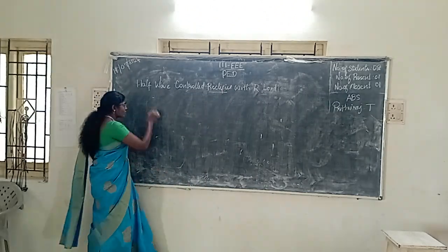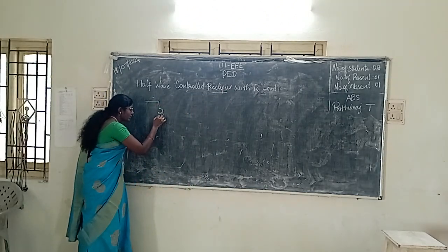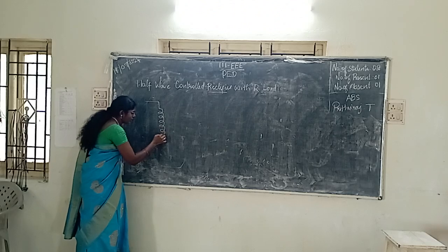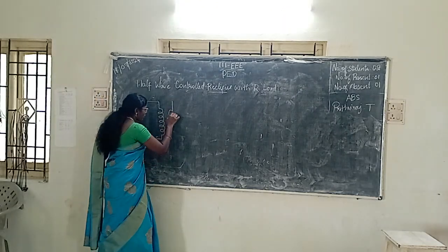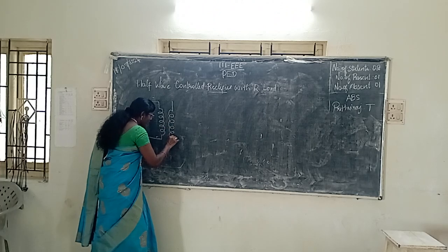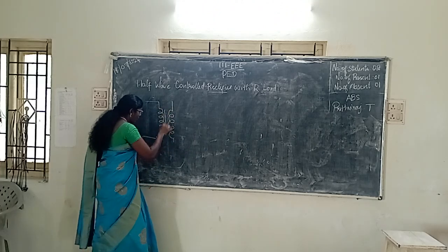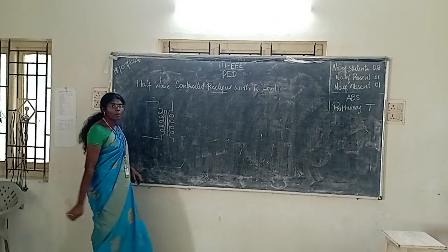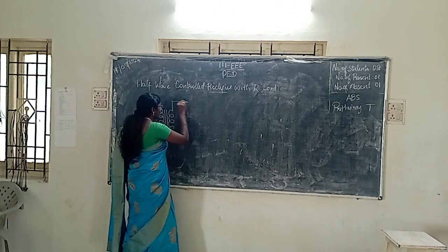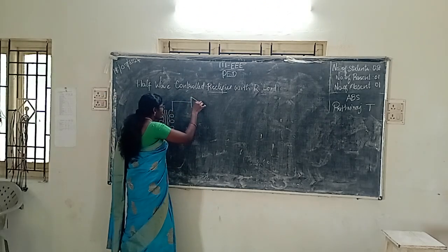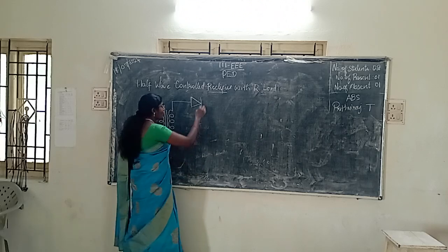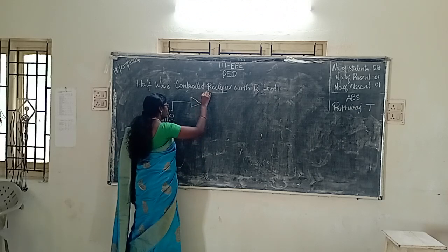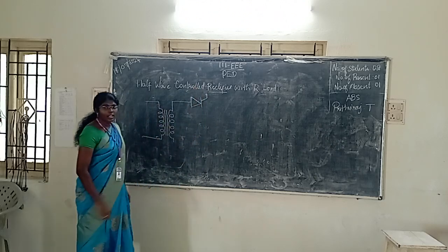You know the concept of the half wave rectifier. On our input side there will be the input source, which we will give to the transformer. We will have the primary and secondary windings across the transformer. Later we will have the switch to control the rectification conversion. Here we are using the SCR thyristor.